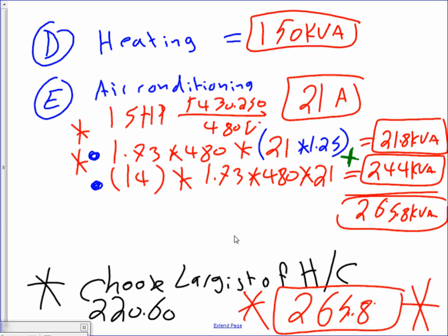Let's go to the heating. Gentlemen, where's my heating and cooling? Would this count as a neutral? The heating and cooling, the demand, right here, where the demand is. Does this count as a neutral? Remember, these are 3-phase equipment. I don't want to write N. Everything here is three-phase. So what I'm going to do right here is just put an X, green X. It would not count as a neutral.